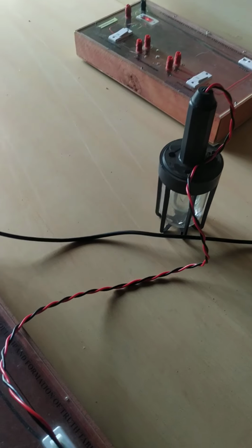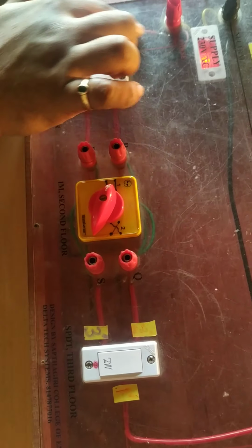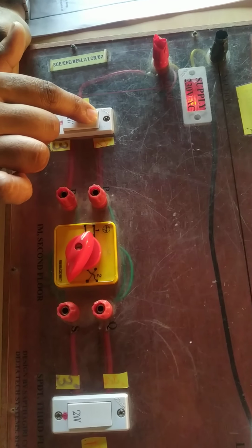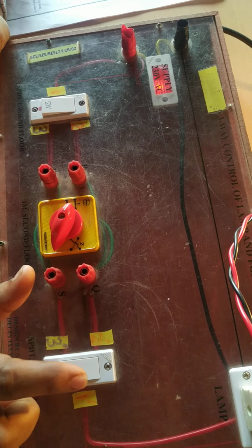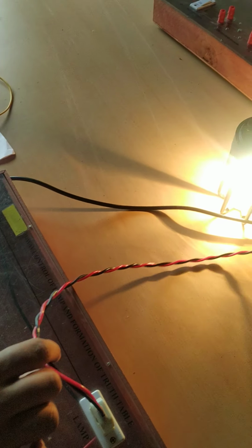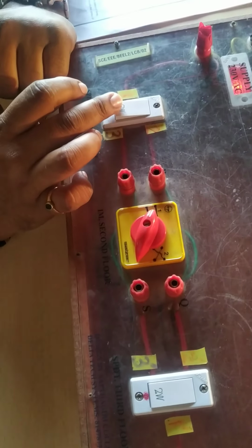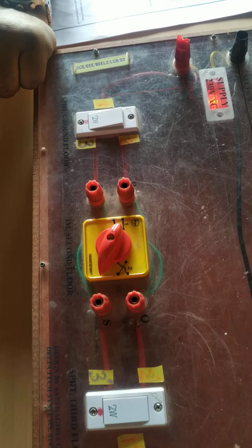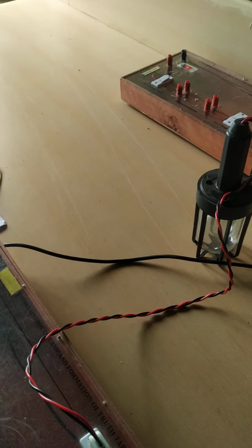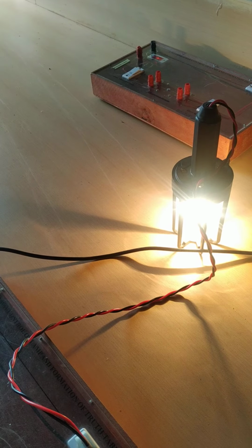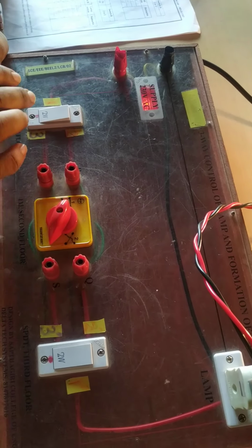Right? Now what I do, I'll change switch B position to 2. Now what happens, supply comes to the one terminal, comes to P, from P to Q, Q to 2, 2 to switch B, and it flows towards the lamp. Therefore the lamp is turned on. I'll change the switch A terminal to 1 dash. The lamp turns off because it becomes an open circuit. Now I'll change the switch B terminal to 2 dash. So the circuit is closed and therefore the lamp turns on. So this is for straight connection.